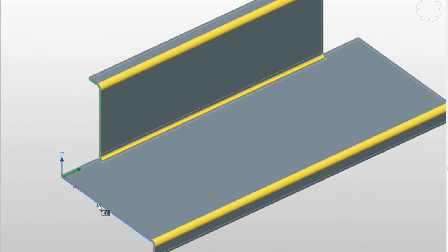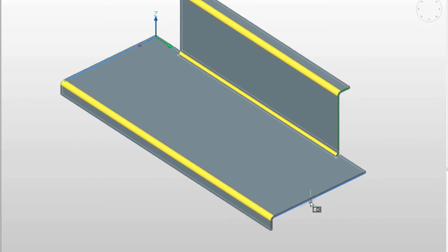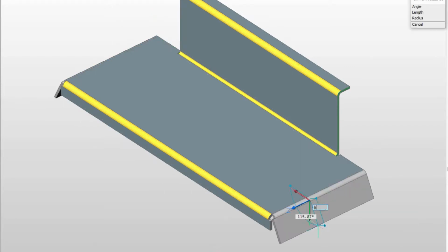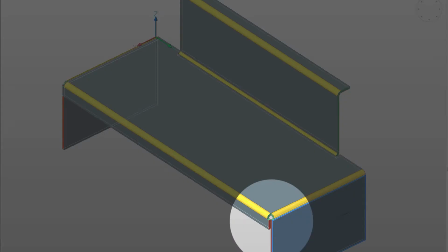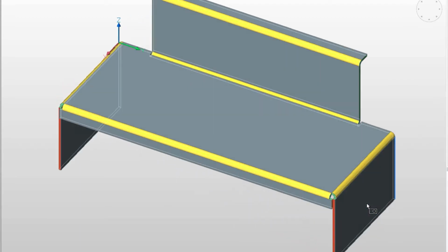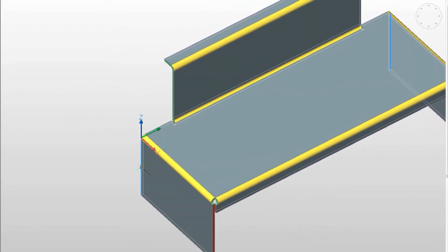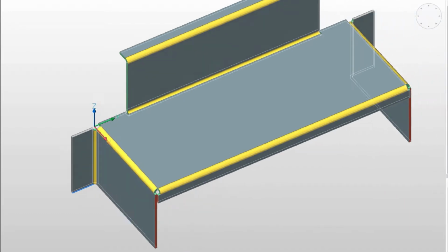Let's create multiple flanges simultaneously. Select several edges and you can really accelerate your design process. Notice that corner reliefs at junctions are created automatically. This trick comes in handy. We can create symmetric flanges in seconds and modify each of them individually in BricsCAD Sheet Metal.